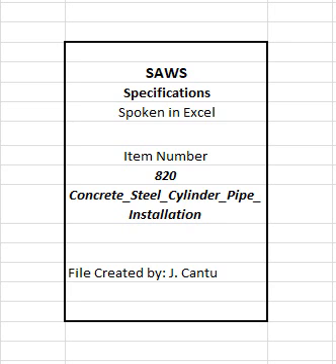23. Weld testing. A. Perform macro etching tests for complete penetration production welds on normal production weld tests. 1. Complete joint penetration welds are defined in ANSI/AWS A3.0. 2. Verify complete joint penetration by means of macro etch of joint weld cross-section. Macro etch technique in accordance with ASTM E340.